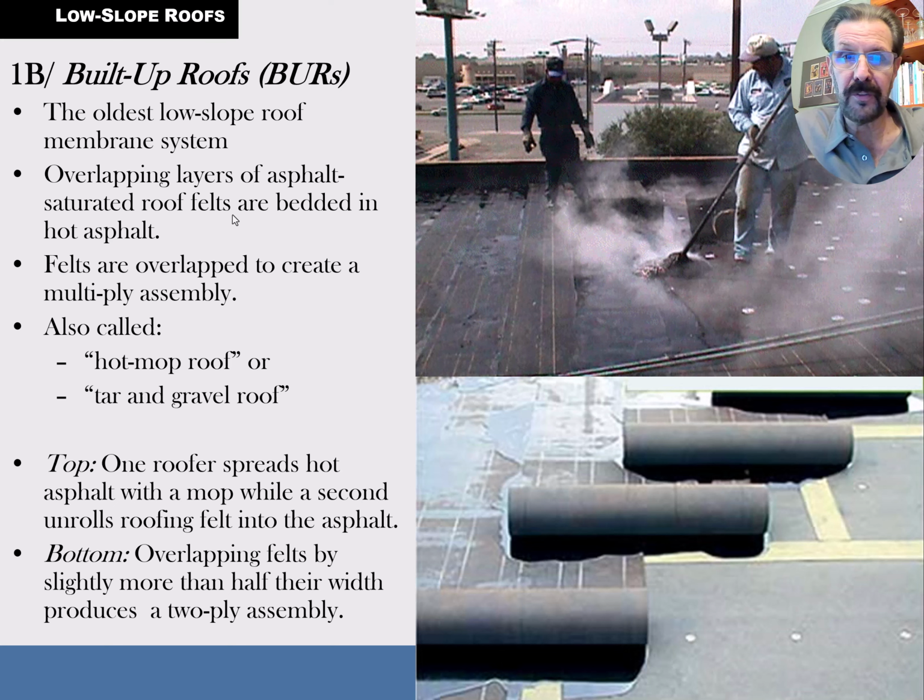So you don't want that on your skin. So you see these 2 guys, it might be hot out there, especially working around this stuff. They're not in shorts and a t-shirt. You're going to have clothing on, long sleeves, and gloves to protect your skin from burn. Any amount on your skin is going to be a serious burn. So they literally spread this stuff up in a team. It usually takes a team of 2 or 3 people and maybe somebody on the ground that's heating this stuff up and pumping it or bucketing the stuff up to the roof where it's mopped around through the layers of paper.